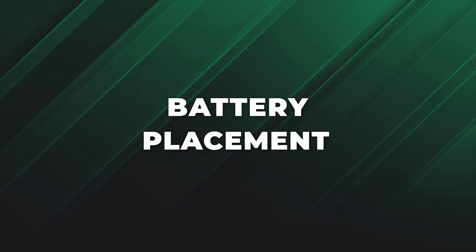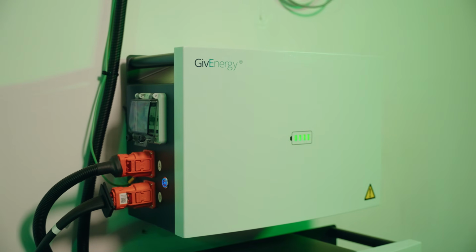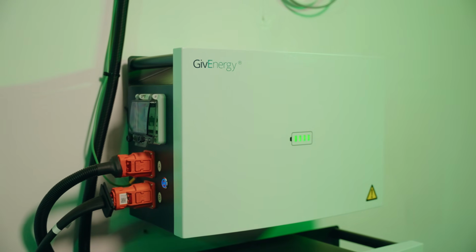Inside, outside, where should you be installing a piece of battery storage? Is it okay to put it up in an attic? Such a common question I get. My personal recommendation would be not to place battery storage up in the attic. It's very awkward. If you've got an inverter already in your attic, I'm going to circle back if you're thinking of adding battery storage in a second. This is on the basis it's a fresh and new install.